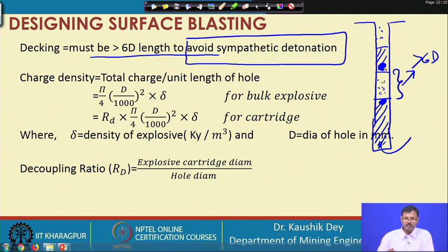So, to avoid this sympathetic detonation, the deck charging length must be greater than 6 D, 6 times the diameter of the hole.